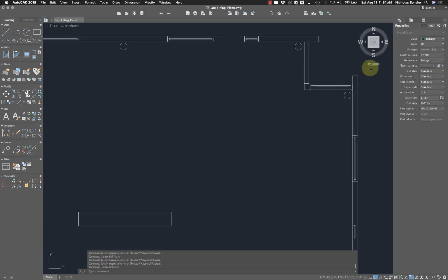You'll notice that everything in the drawing is on the same layer, as I talked about in the other video. In order to put things onto layers to give them line weights, you want to select them, and then you can change their layers. I am going to leave it up to you to determine what layer, what line weights things need to be based on the spatial hierarchy.